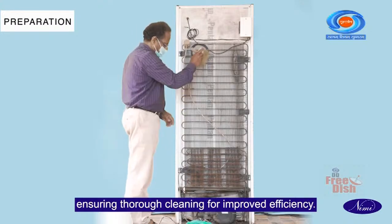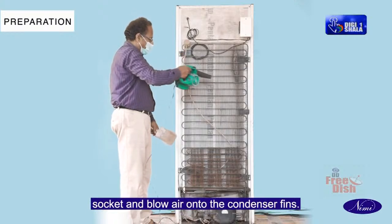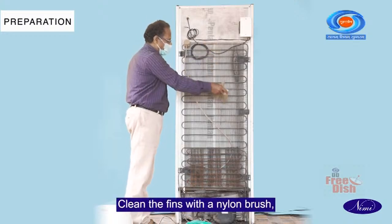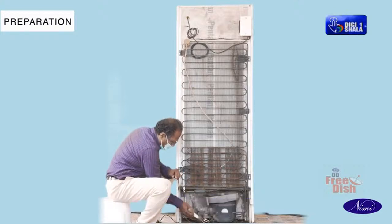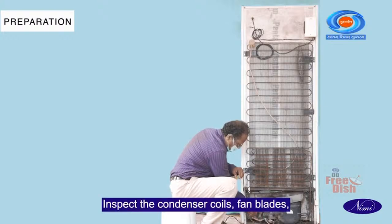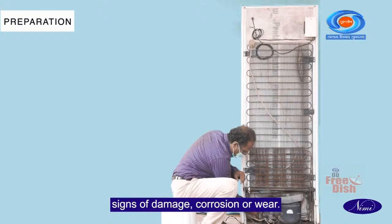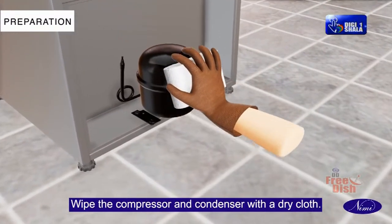Brush or vacuum gently in the direction of the coils to prevent damage, ensuring thorough cleaning for improved efficiency. Connect the air blower to the socket and blow air onto the condenser fins. Clean the fins with a nylon brush, including the compressor, to remove dust. Turn off the blower. Inspect the condenser coils, fan blades, compressor, and electrical connections for any signs of damage, corrosion, or wear. Wipe the compressor and condenser with a dry cloth.